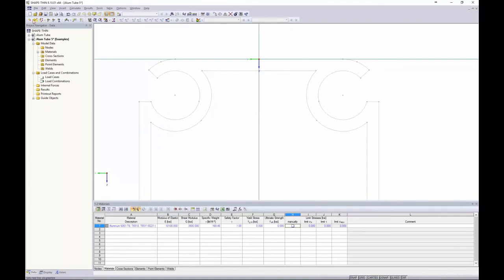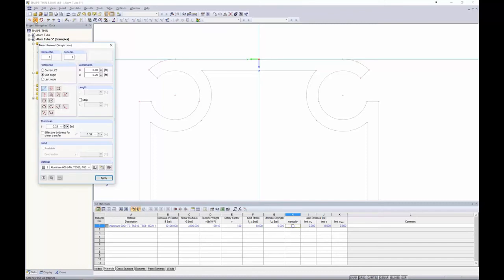Now, the first option we want to go to is this new line up here in our tools. We have a straight line selected here, but I'm going to select a thickness of 0 inches. So all I'm going to do is to snap to one of these points on my arc and snap to the other point that's perpendicular to it. Now, a lot of AutoCAD-like features such as snap points, perpendicular, parallel,